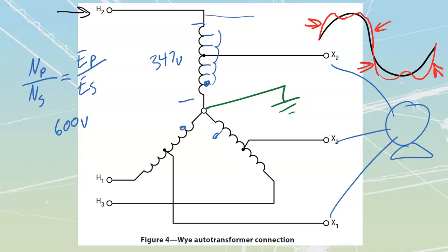What you can do in some cases is have a specialized set of windings called tertiary, or extra windings that allow us to cancel some of that out. We're not going to go into them, but they do exist for some of these applications where it's critical that you use this transformer, but you also have those third harmonics that are already online.